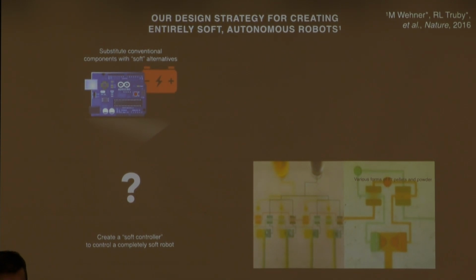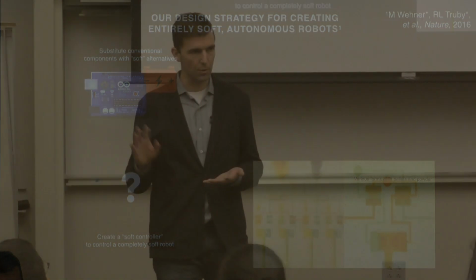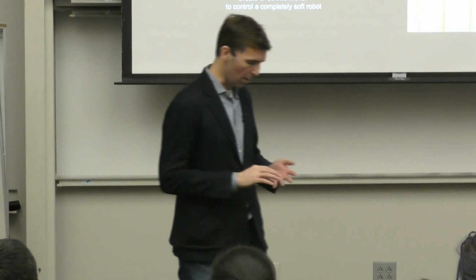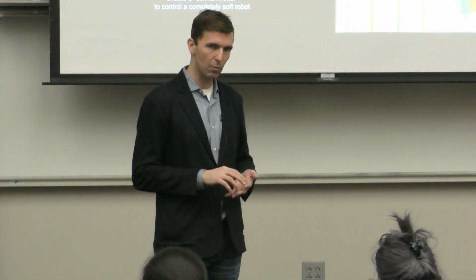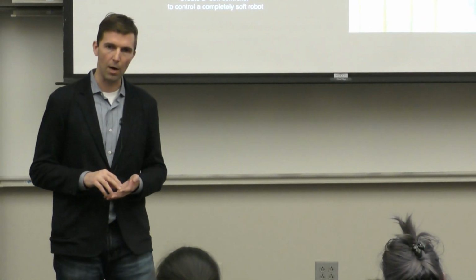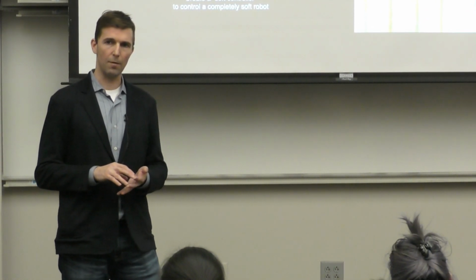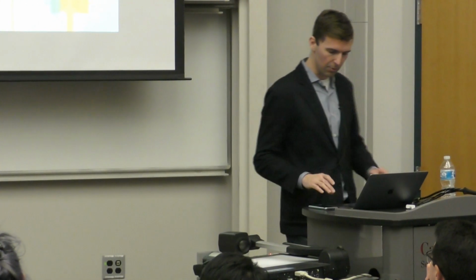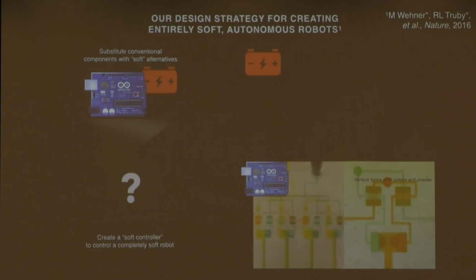I've already showed you how to make soft actuators. That's not new. I haven't told you about soft sensors, but we can do that too. Mixed phase fluid elastomer sensors, whatever. We can do that too. The things that we really haven't told you about are, how do we make a power system soft, and how would we make a control system soft? And control I'm using very loosely here. And so for those two questions, we studied the following.